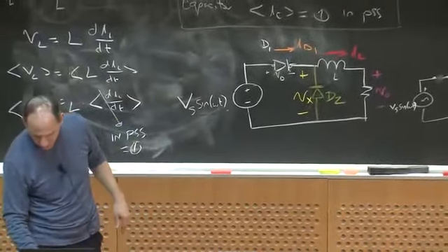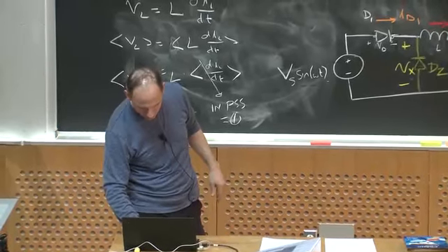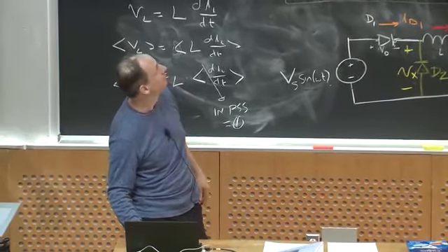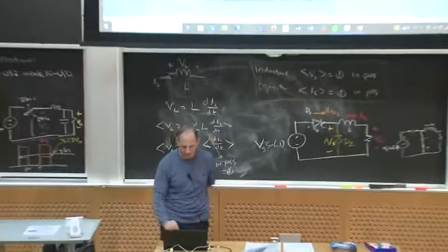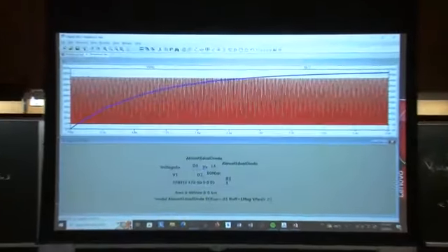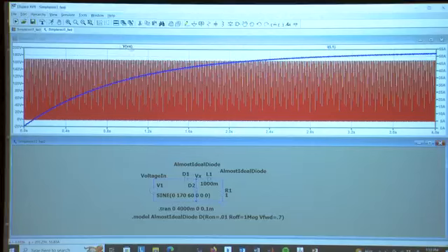If I put down this simulation, I'll put up my other simulation. All we've done here is add a second diode. This is what's known as a half-wave rectifier. Let me show you two things. First of all, you can see Vs sine omega t here is this red, which is on the left axis. I'm sorry, this is V sub x. This is my yellow waveform over here.